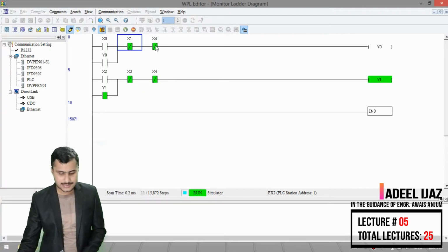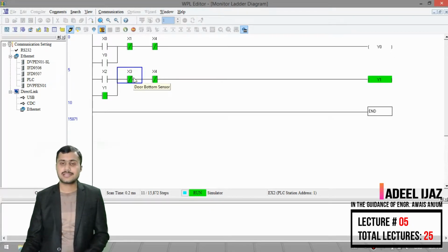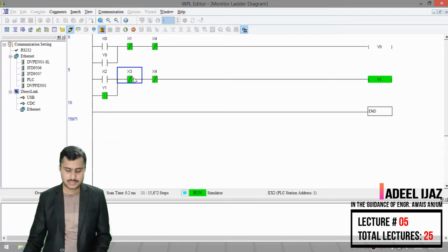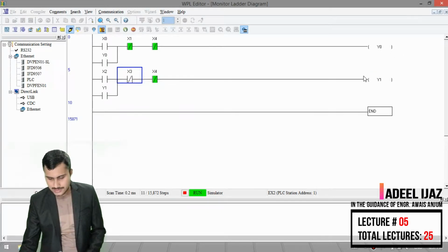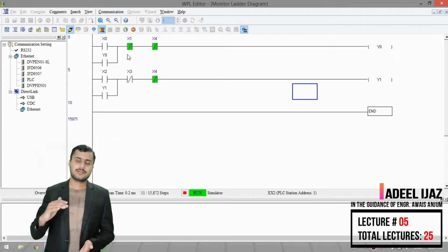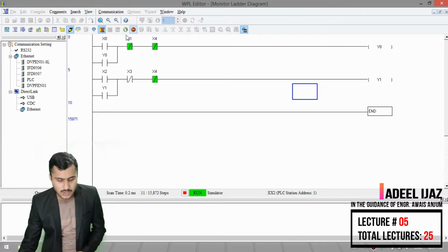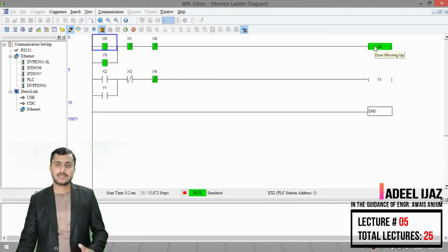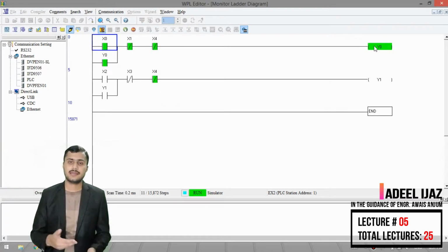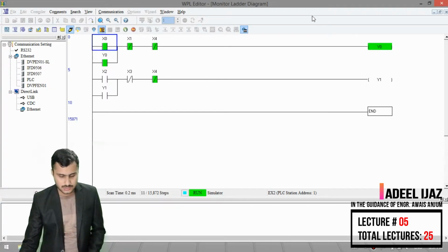So our X3, which is the sensor attached at the bottom of the door, is now activated. If it is activated, you can see the door stops moving in downward direction. Now we want to open the door again, so we have to turn on X0 again, and you can see the door is starting to move in upward direction, and again the sensor attached on the bottom of the door is now disengaged, so